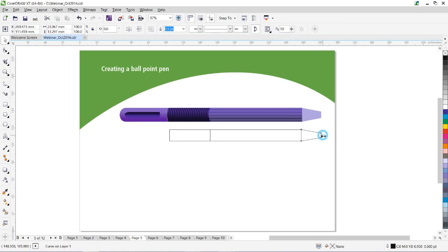This I'll duplicate and mirror. While mirroring, if I'm moving this, it transforms as I move it. The moment I press Ctrl, it gives me the exact mirror of this, and I am duplicating this. Moving from here, again a modifier key. If I am moving without anything pressed, it moves wherever I want. But the moment I press Ctrl, it moves only on a straight horizontal or vertical line. So pressing Ctrl will give you exact movements of the objects.